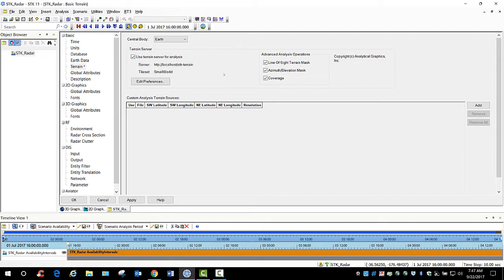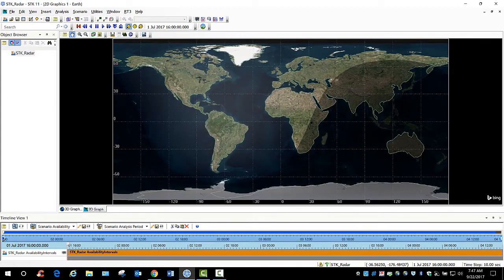So now we have analytical terrain running, and if you haven't used Terrain Server previously, it's bringing in both visual terrain and analytical terrain for the whole Earth. So I'm going to go down to the bottom of my GUI and click OK and select my changes. I'm going to save often. You don't have to wait for me to say save. Save whenever you can think of it. I'm going to go ahead and save.